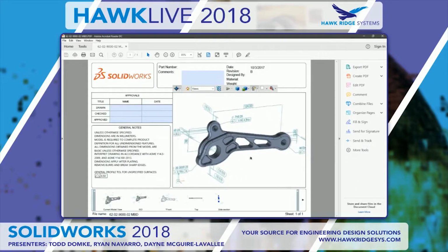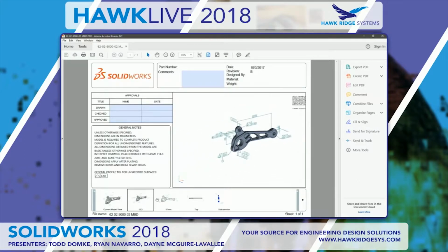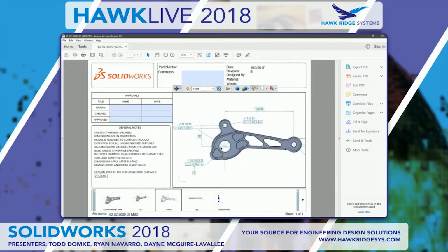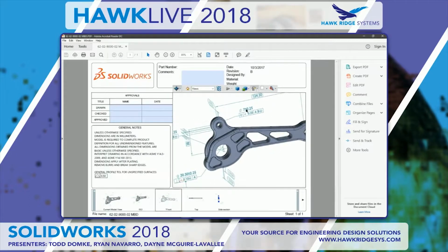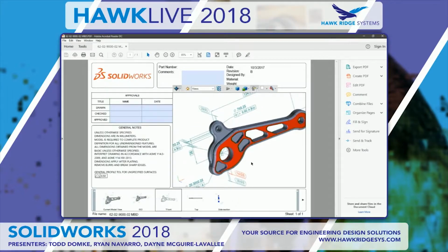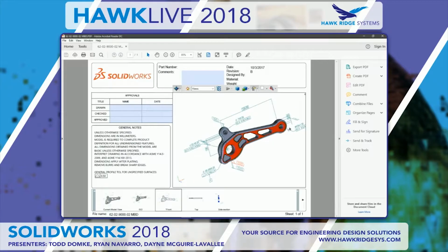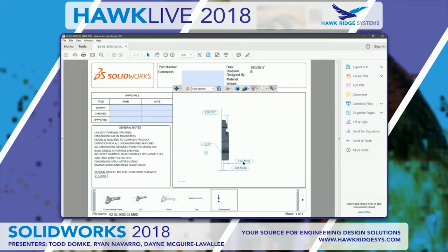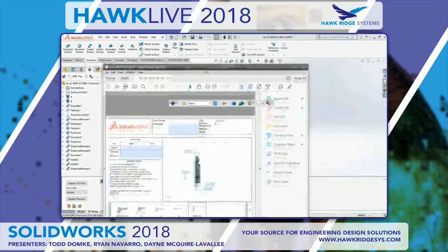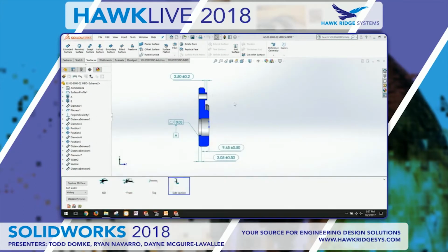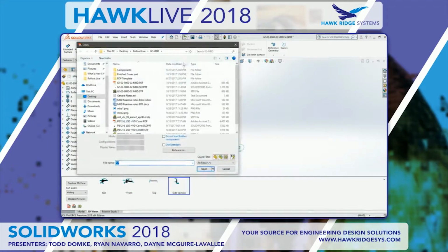Basically, it's just a screen where we can rotate the model and access those different views. And the great thing about this is it's going to reduce interpretation errors, because if you click on any of these dimensions, it's going to highlight for you the datums and the references that that dimension is between. So things that you just could never get on a 2D drawing, thereby getting the context of these dimensions. So that's some of the new things there for 2018. And also with MBD, it's now allowing us to also import those files into SOLIDWORKS with PMI.